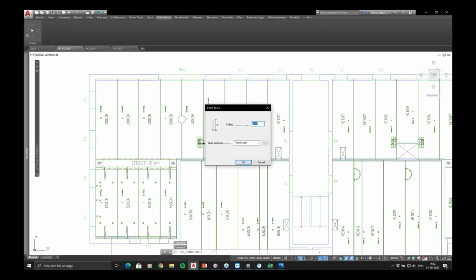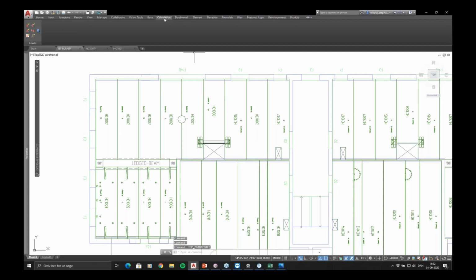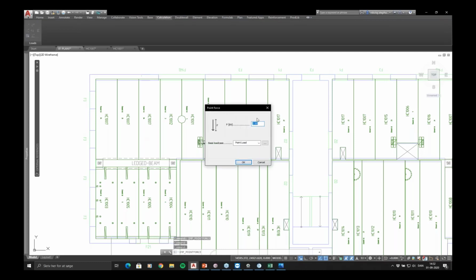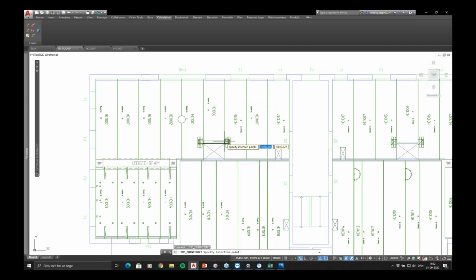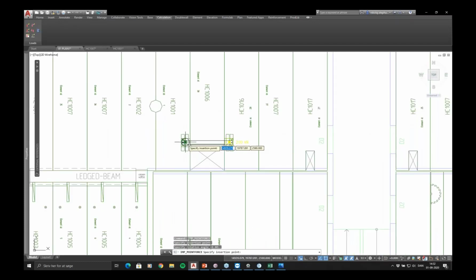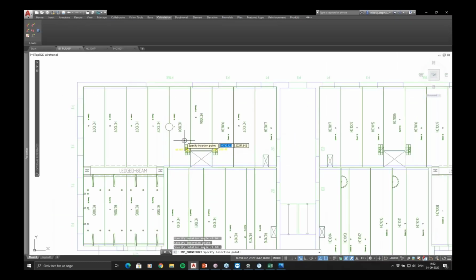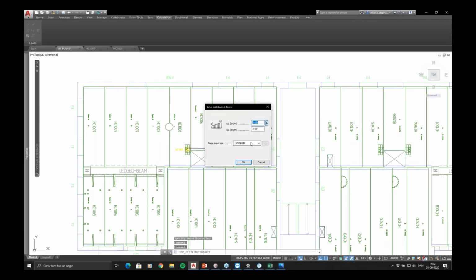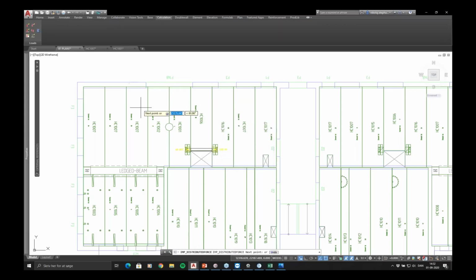What I do is I click the point load button up here. For those of you who are very quick, notice that I jumped over to a tab called calculation. Click this one here, add point loads, here and here. Maybe I have a wall above that is standing directly on the Hollowcores. This is like a gypsum wall, it's not so heavy. That wall will be placed here.